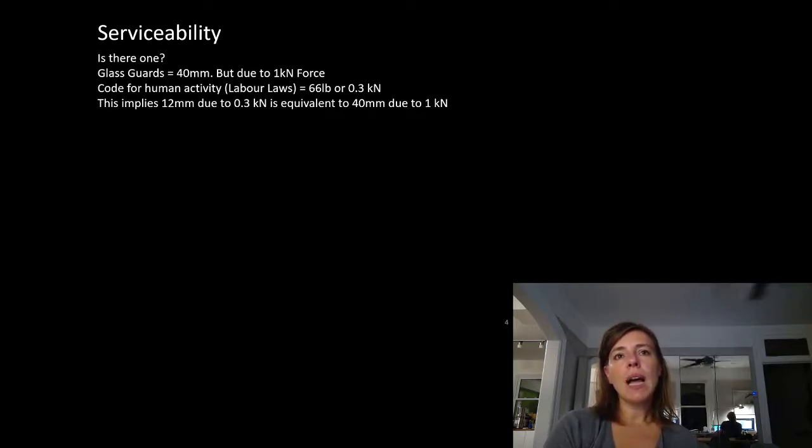So often I will discuss this with the architect and let them know the lower and upper bounds of what it is, and then what the actual criteria is. To be honest, most guards that I end up designing, I just make them match, because architects often have the idea of exactly what they want in their guard. Usually I'm not generating the sizes, but checking that the sizes they want to use work.